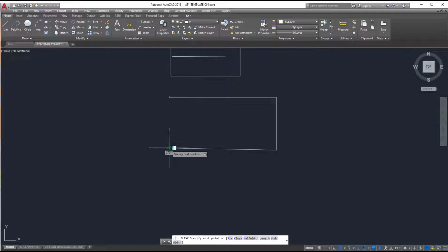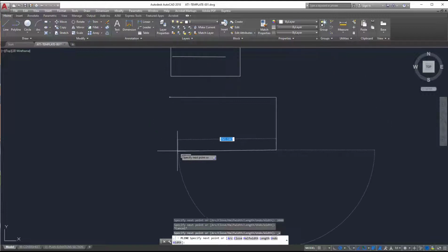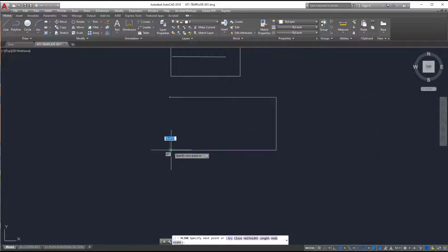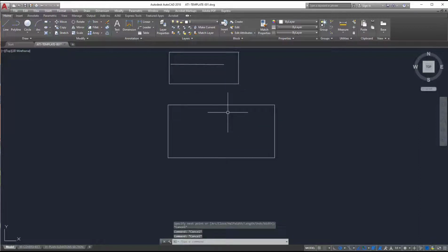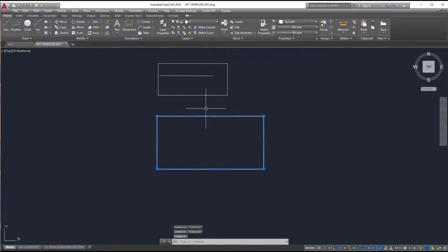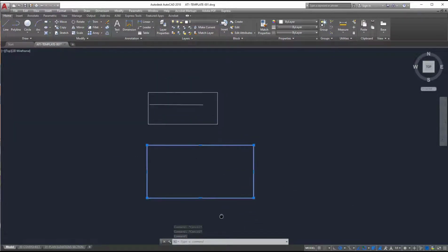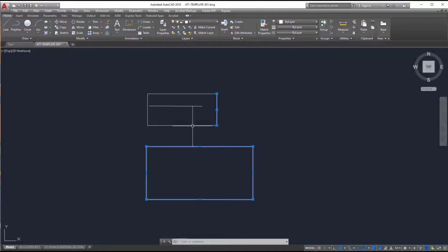And you can see, I've drawn that on an angle accidentally, I just hit Control Z on my keyboard and it will take me back to the last line. And then complete the loop and then hit escape. Now when I go to select this rectangle, you see that it selects as one item because it's a polyline. So it's one closed curve, one closed line, rather than 4 individual lines.